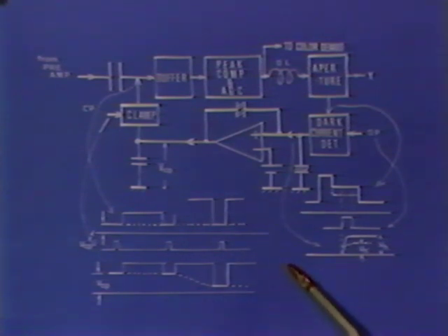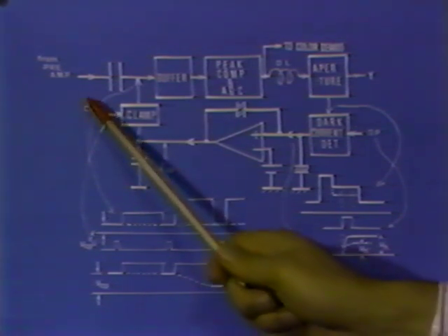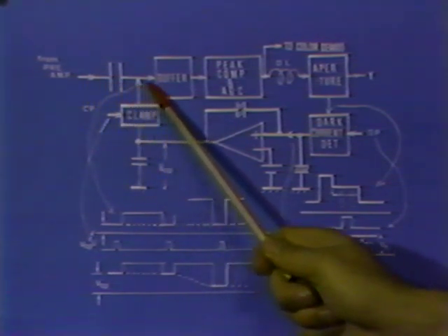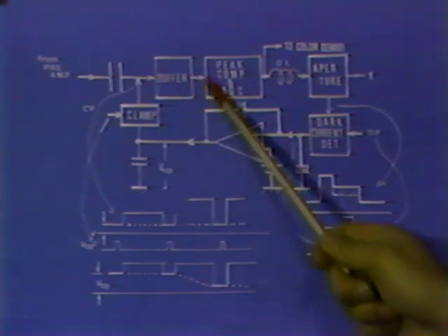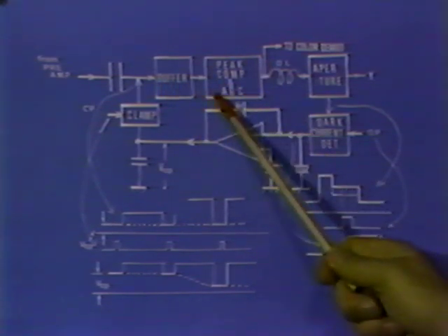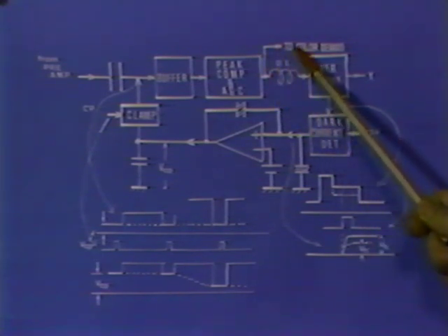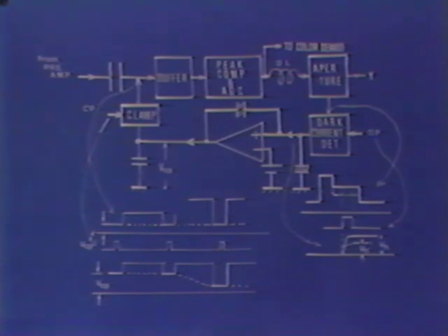This figure is the block diagram of the dark current compensation circuit. The signal from the preamplifier is processed in the preprocessor and goes to the luminance signal processor and the color signal processor, respectively. The Y signal, the lower frequency component, takes care of the dark current detection.